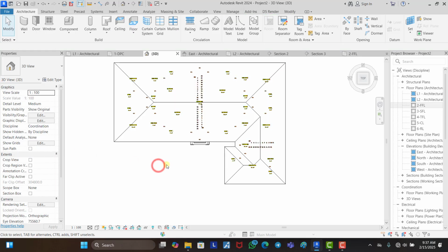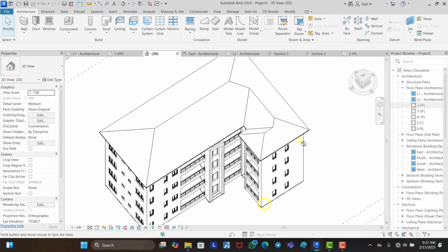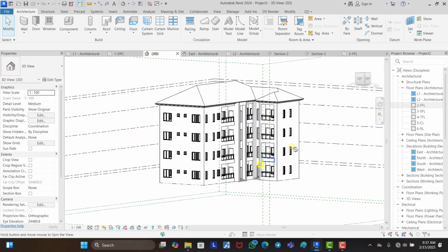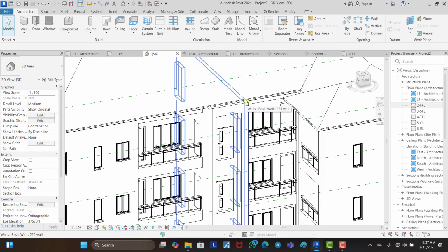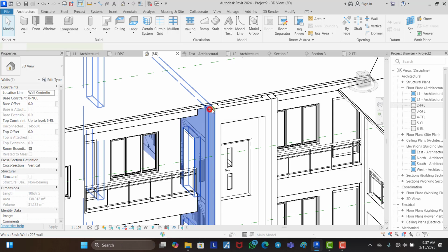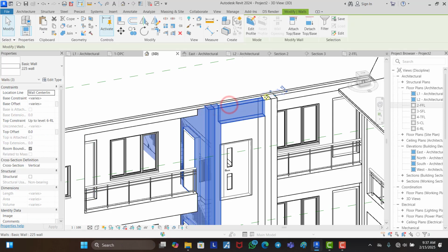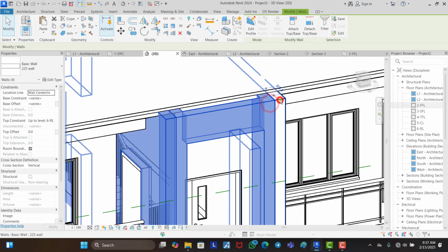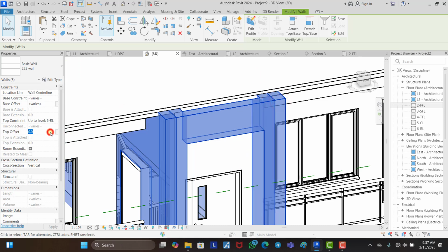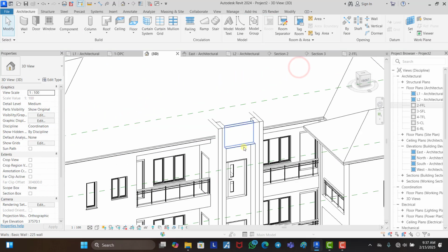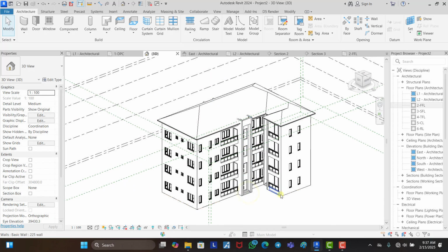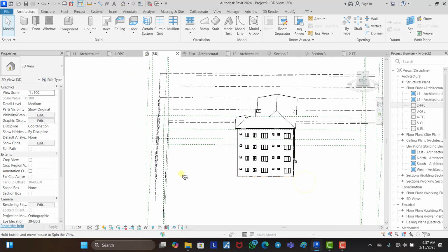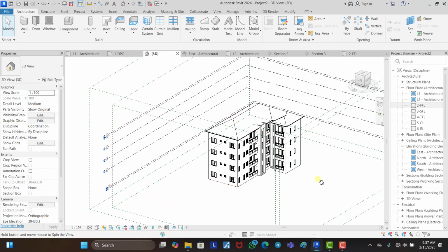All right, perfect. Now we have done our roof, so you can check this out and you can see how the roof is. Good. Now you can see the front. The front is a little bit different. Good. So this front needs to go up slightly by 600 mm, just to create a different roof design for it. So you can see top offset. Let's make this 600 top offset. Okay, it goes up 600. Perfect. So we can have a separate roofing for this. So we'll work on that shortly, but you can see how this looks. This is looking okay. Good.